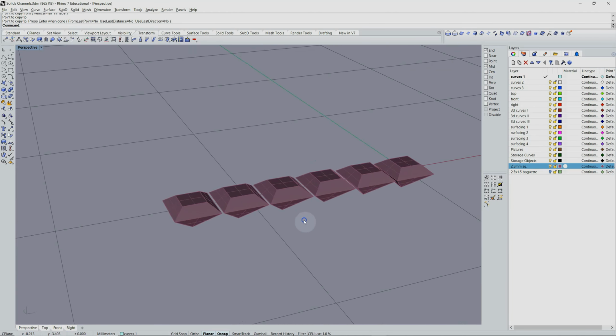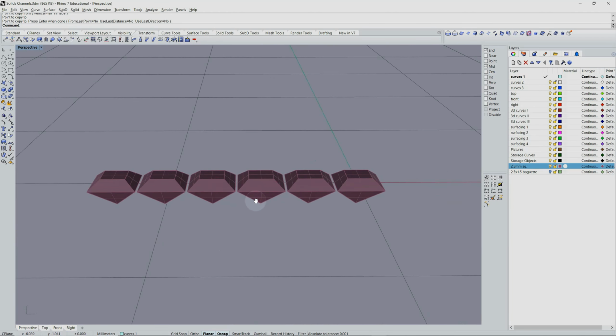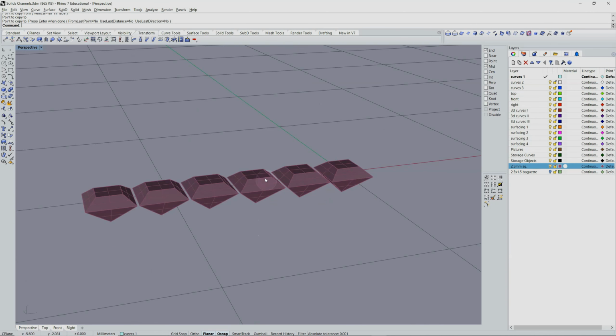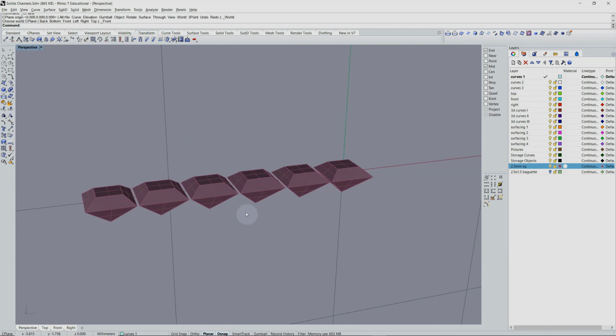Models should always be built around world center. In order to center up my layout of stones here, I'm going to be using a circle that I create using the circle diameter. I'm going to want to draw this circle vertically using the front C-plane. So activating front C-plane by going to the Curve Tools tab, I'm going to choose the Circle Diameter command from the side toolbar.